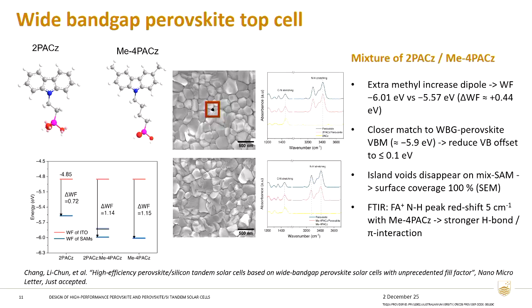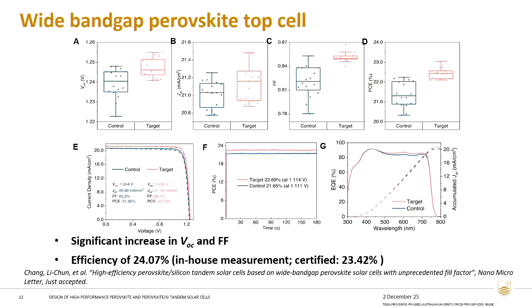That allows us to have such a complete and higher quality perovskite film without any voids. So this allows us to not only improve the VOC, but also simultaneously improve the fill factor, which has been a challenge for the perovskite solar cell, because usually when we want to improve the VOC, we adopt passivation technologies like using 2D perovskite material or inorganic material that usually are not conductive, so that usually the VOC enhancement comes together with the sacrifice of the fill factor.